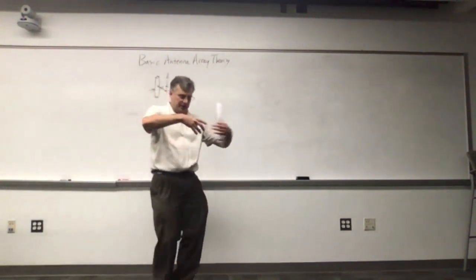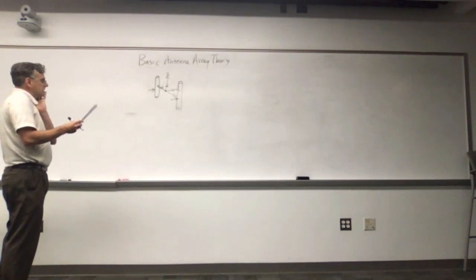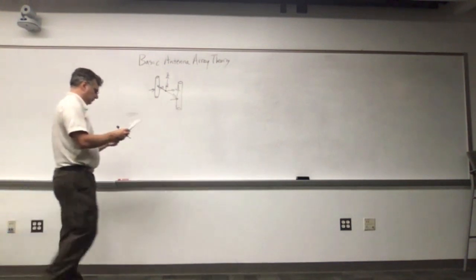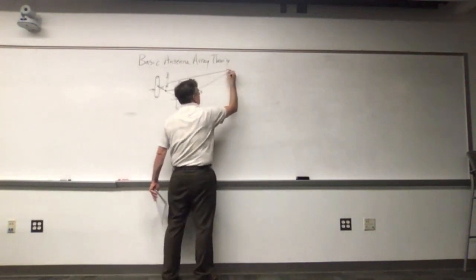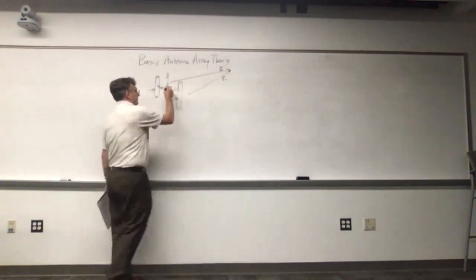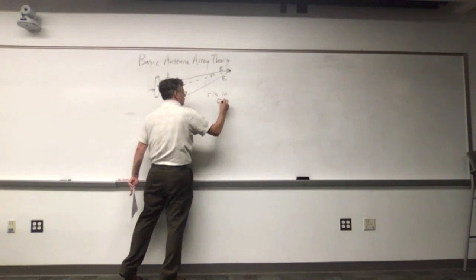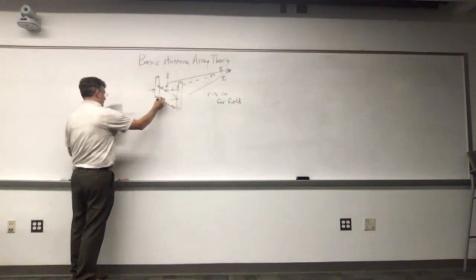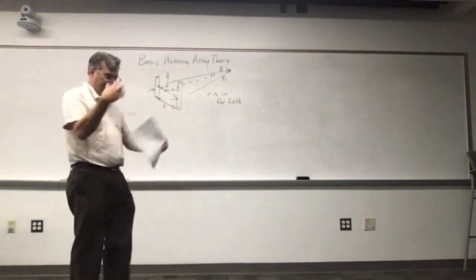Each individual element is omnidirectional and would put out, to a particular location, each individually, a field with magnitude E0. If we are in the far field, in other words, we're observing this system more than d squared over lambda away, where little d is the variable I'm using in this analysis, then I'm in the far field.